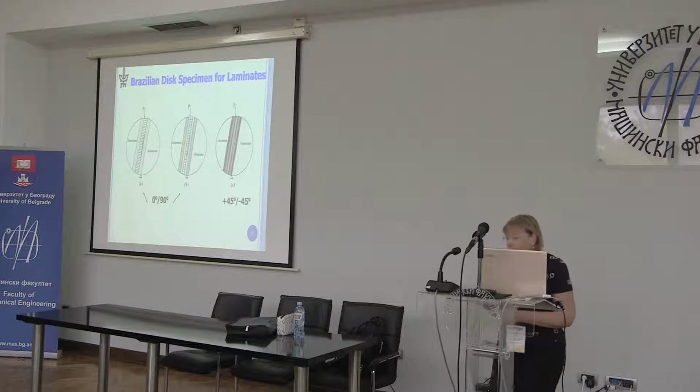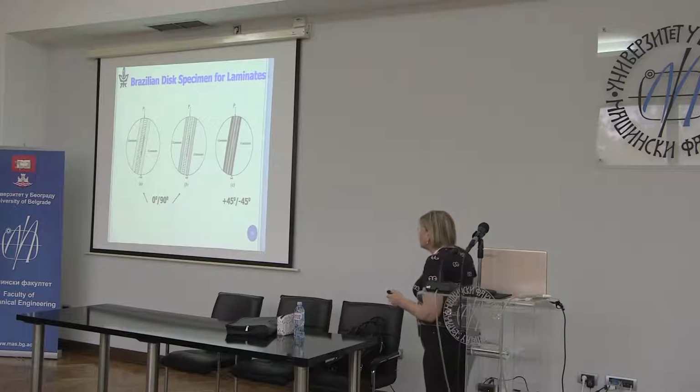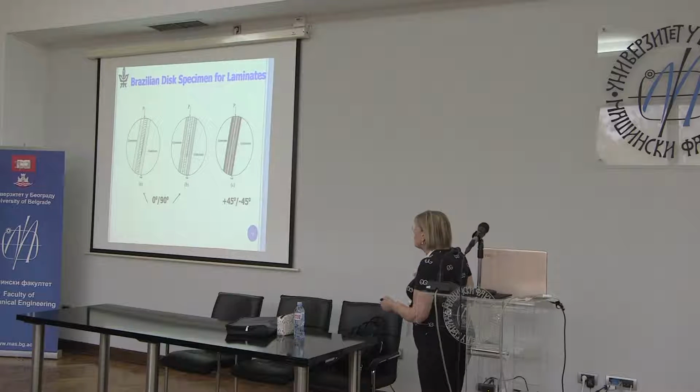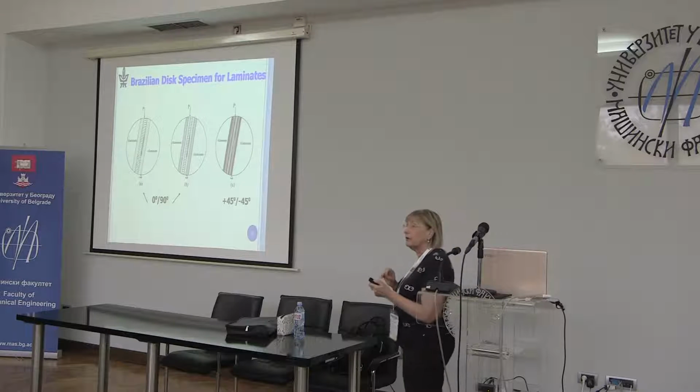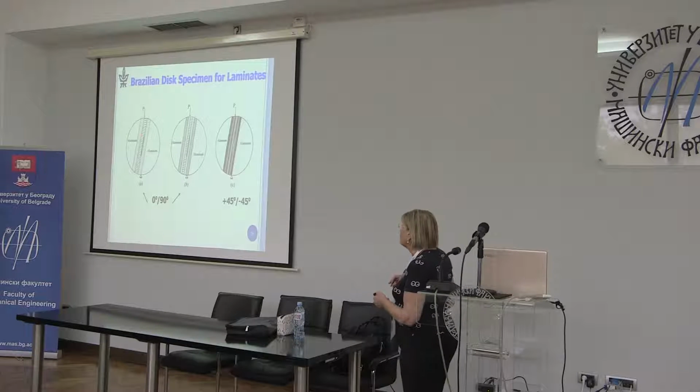So now I'm going to talk about resilient disc specimens, which have a strip of composite material. These are the same as the specimens I showed you, glass epoxy. They're 40 millimeters in diameter. We have a notch made by Teflon of between 10 and 25 microns.